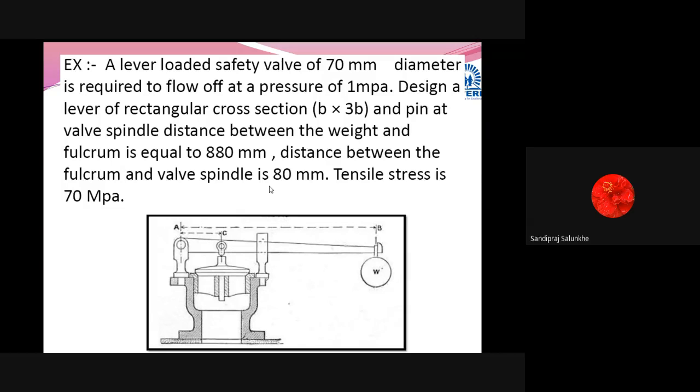Then design shear stress. Okay, tensile and compressive are considered as equal. If it is not mentioned in the problem, you consider it as equal. If it is mentioned in the problem, then you take the recommended values or given values.